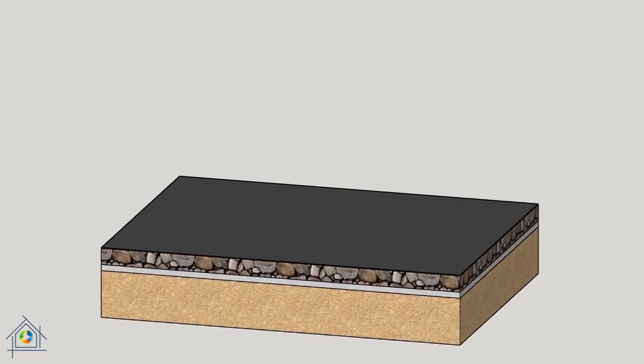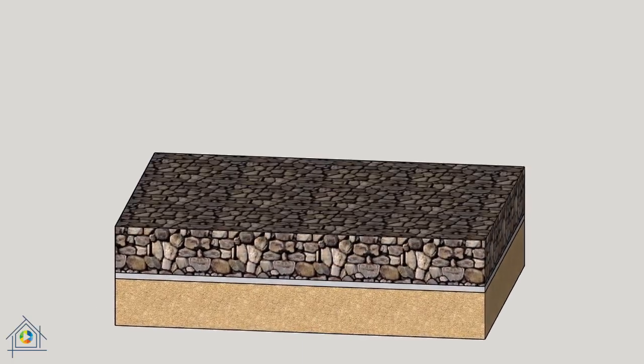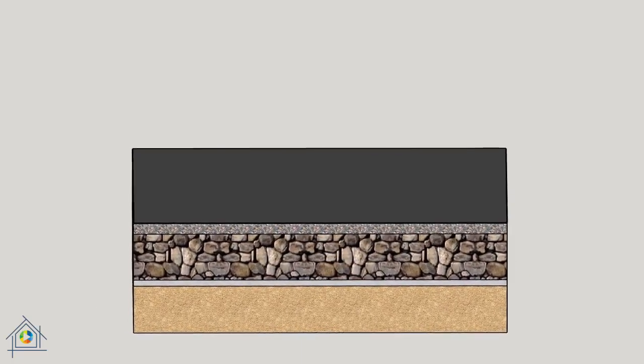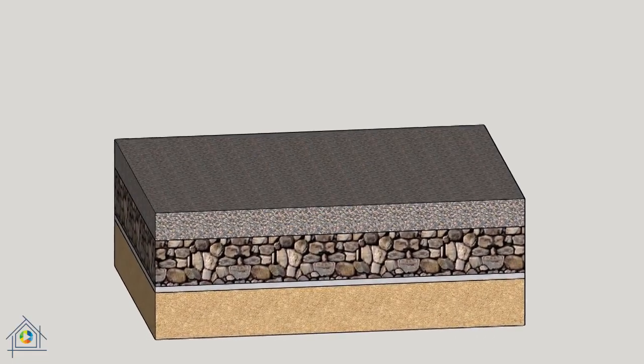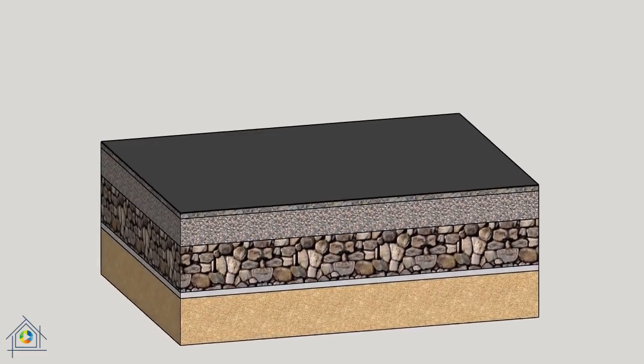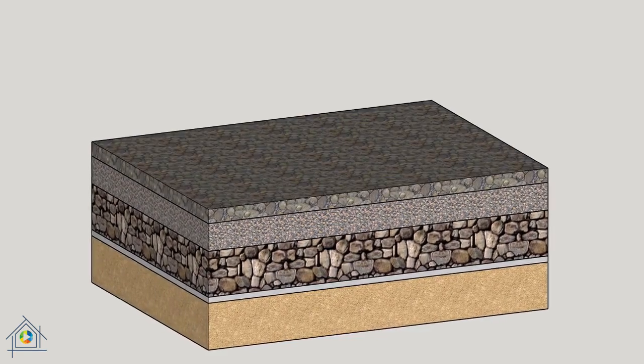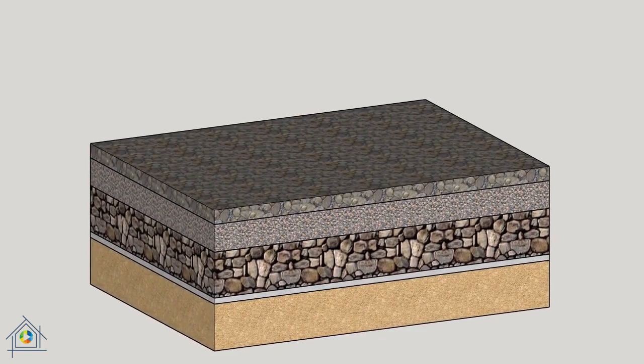To prevent soil moisture from transferring to higher levels, several layers of dry stone are used. First, large pieces of stone, then smaller pieces of stone with a thickness of 7 cm, and finally a sand and gravel mixture with a minimum thickness of 1 cm are poured into the flooring area. The total crushed stone layer is between 25 and 45 cm.